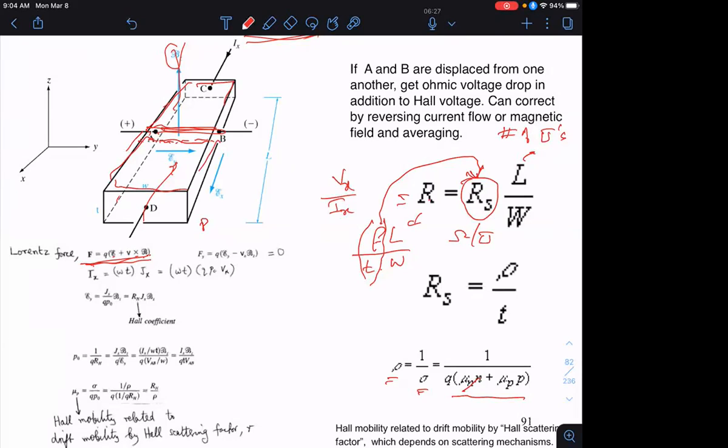And it doesn't matter to the resistance whether I double the length and double the width, the L over W term will still be the same. And the resistance will be given by this sheet resistance times the geometrical layout. So that's a different way of writing the same expression, but it's interesting because it allows you to break down the value of the resistance as a process-dependent term, meaning things like the resistivity and thickness of the film, times the geometrical layout of the resistor, how long it is divided by how wide the film is, okay?